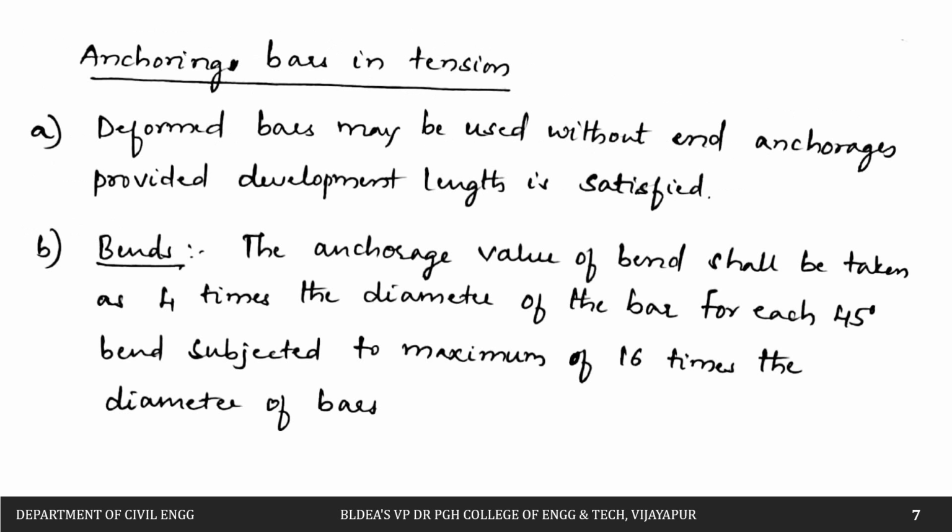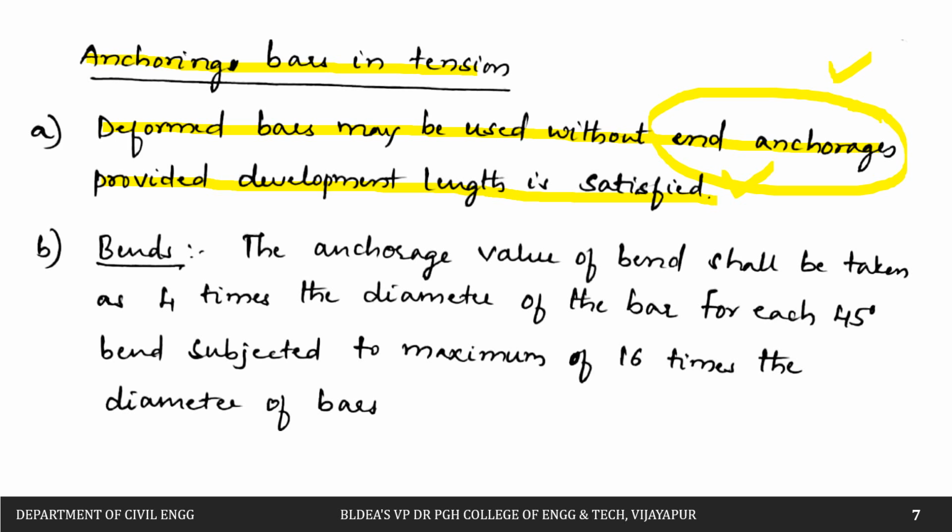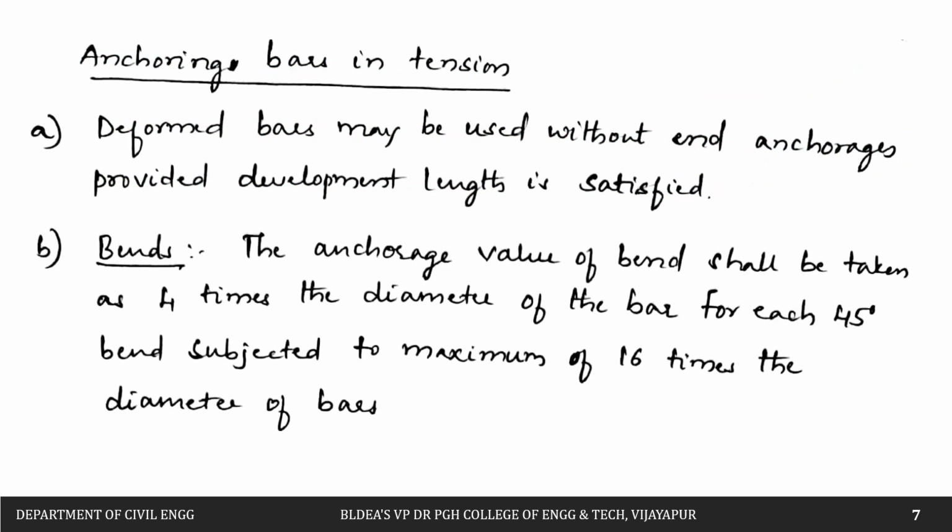Then next is anchoring bars in tension. When we are going to use deformed bars, they may be used without end anchorages, provided the development length is satisfied. If the development length is satisfied, we can use deformed bars without end anchorages also.